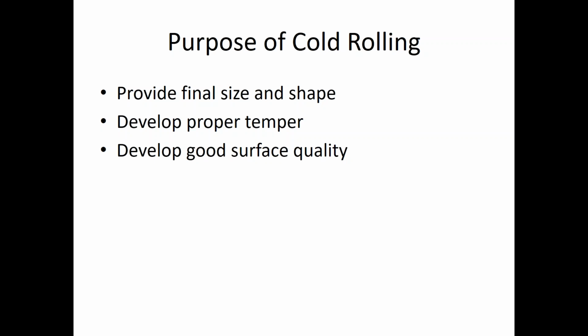Whereas the hot band was very kind of rough, and especially after it was ground on the surface to get the oxides off, what you're trying to do is you're cleaning up your act here. You're going from 3/8 inch thick approximately down to 0.010, say, for example. That's a huge reduction.